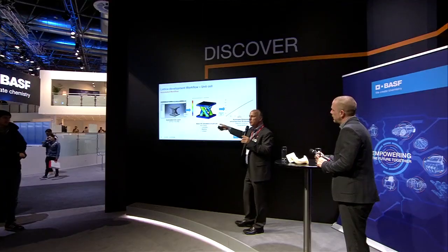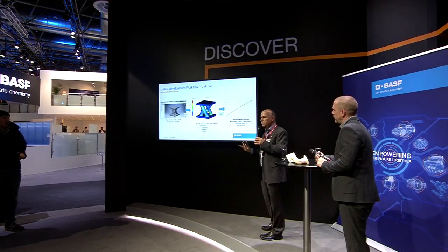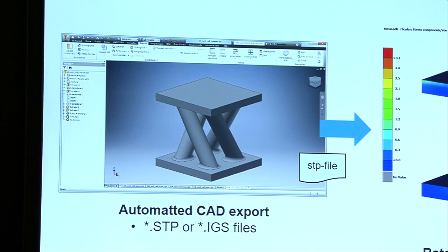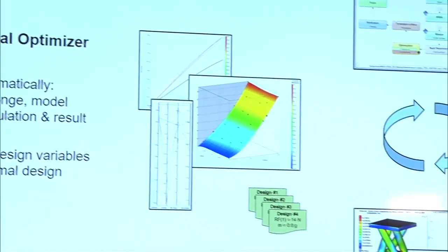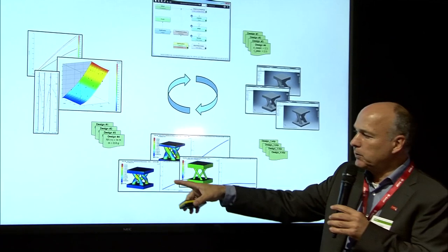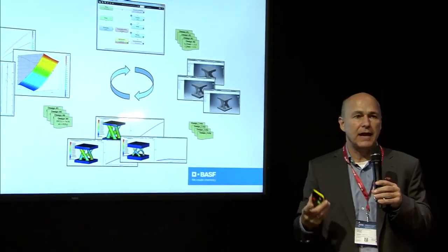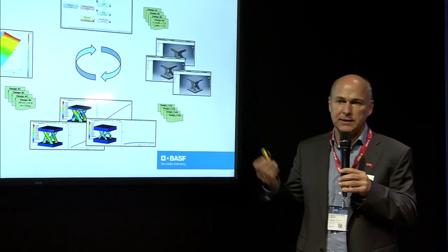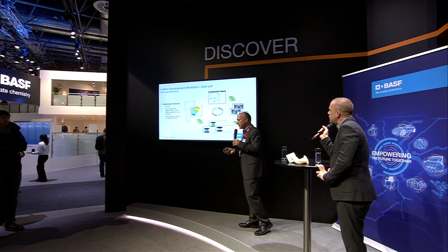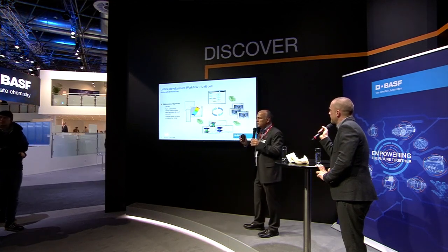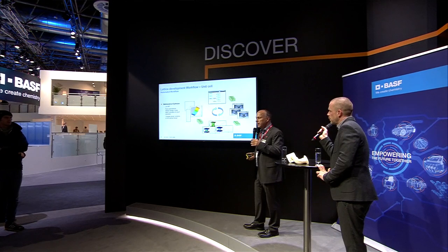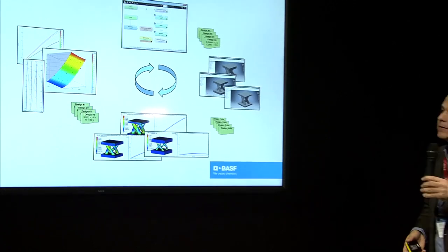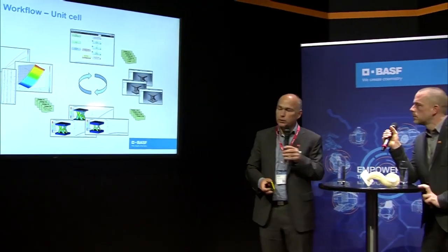We make a finite element simulation in order to find out how this lattice behaves. We can calculate the force deflection curve, and by changing those values, by doing optimizations, we can run an optimization scheme in order to find the lattice that best fits what we want to achieve. So if it's a lattice in a kind of protection, where you have energy protection, or where you want to dissipate energy, or if it's in a shoe sole, all those things can be covered with this technology. And we offer that together with our customers with 3D printing solutions.